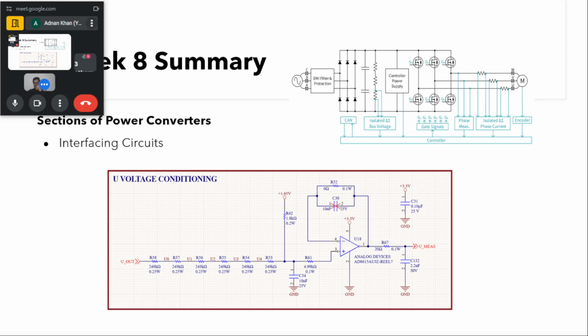sensed voltage. Let us say we had sensed an AC voltage, it will be having some positive and negative values, but we cannot give the negative voltage to this microcontroller. So what we want to do is first give an offset to the voltage.